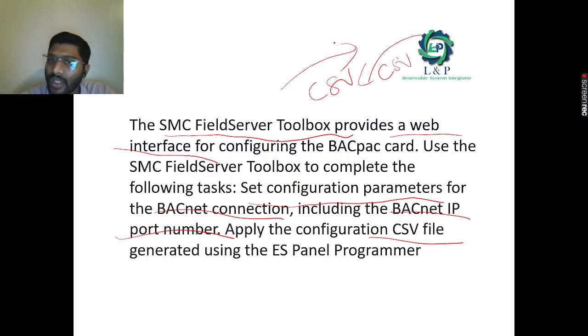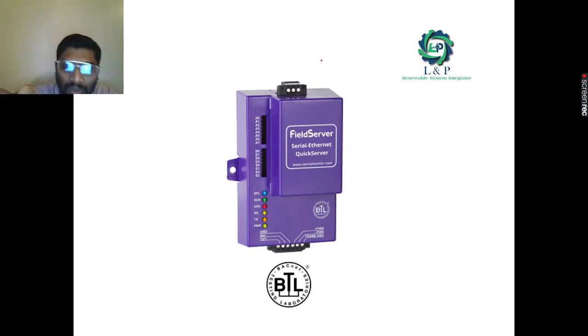While exporting, it might be an empty file, and after updating the required details, that is, the parameters you want, the BACnet connection that you want to establish, BACnet IPs, port numbers, slave IDs, all these things you can assign. Then you can import it and communicate with the different sorts of field devices present in the field. So this is how the device looks.